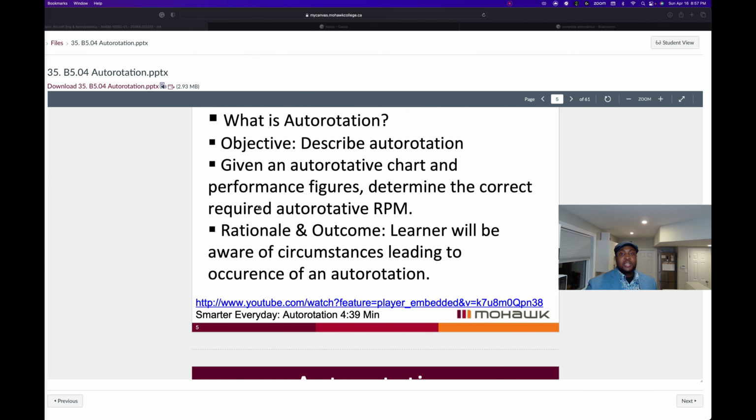So ground resonance is a self-generated out of balance condition in the rotor, often associated with landing, but it can also occur during takeoff or ground run-up. The problem is the result of blade position around the lead lag hinges of the rotor head. So if this blade was to lead and this blade was to lag, you can see that the distance between the two blades would be too small and will cause an imbalance, similar to what you would find in your washing machine. On the ground, the blades can become out of phase with one another. This is the term that we use, which is bunch up.